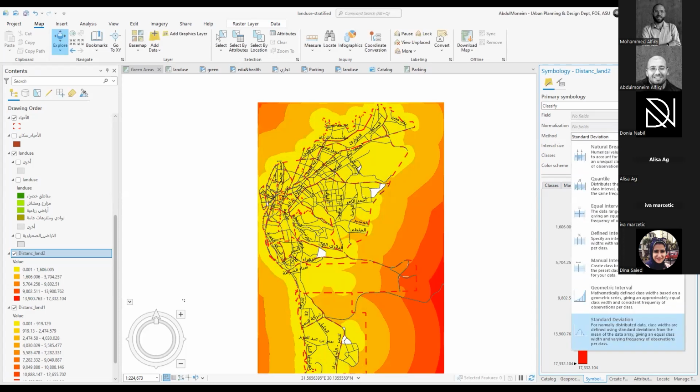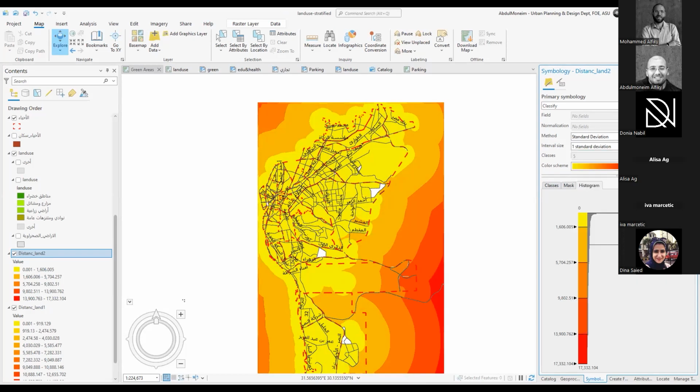Okay, symbology for raster data is a bit different from the symbology for vector data because basically we have cells that have numerical values, and so you get more tools that have to do with manipulating such numerical values. So this is what we get when we do classify.